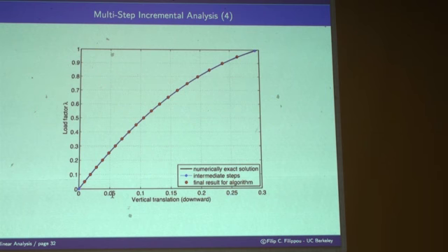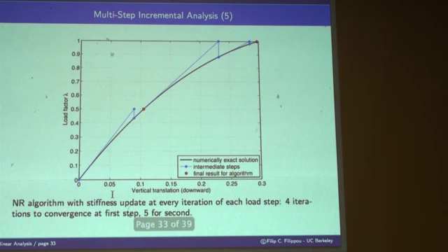And when is the step size very small? When you run an earthquake motion, because your accelerations are recorded every 0.005 seconds. Right? So if the step size is small, many people run dynamic analysis without correction. So don't get hung up on these iterations that I'm showing here, because it may be good enough just to do this. All right.